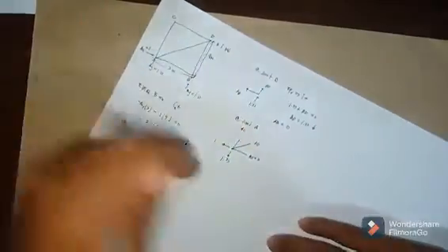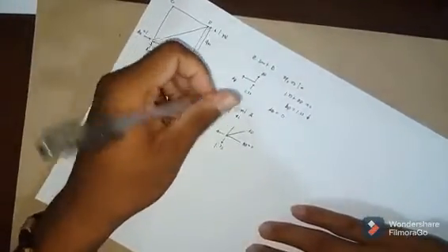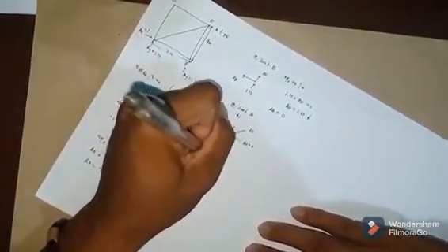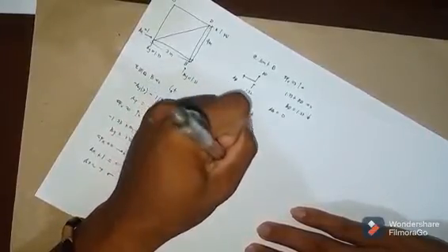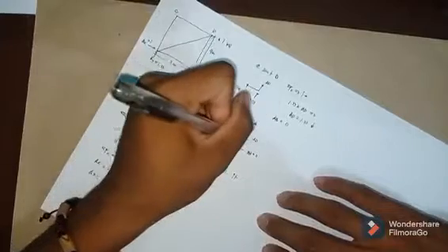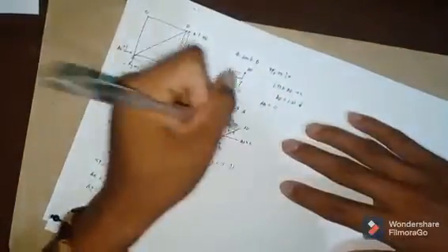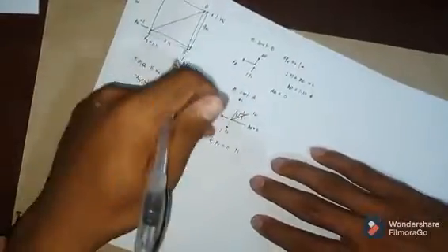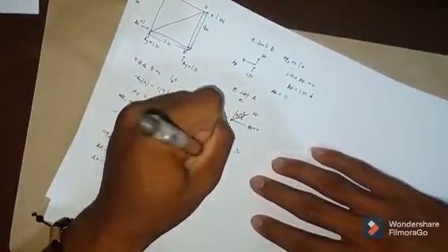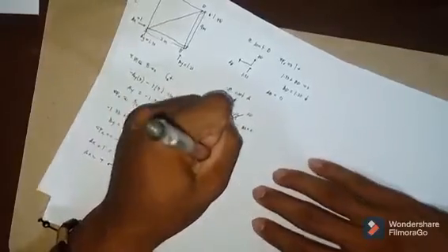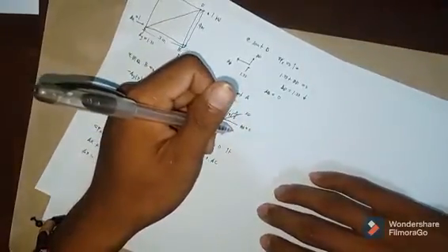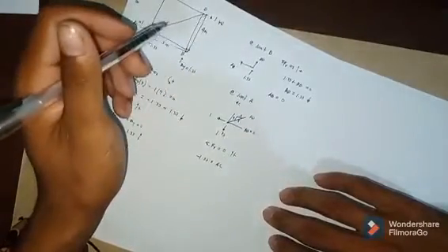So, summation of forces, vertical, is equal to 0. Upward forces positive. Same thing, the length here is rise 4 and run 3, and then the diagonal here, which we solved earlier, is 5. Summation of forces vertically: negative 1.33 plus AC, which we haven't found yet.